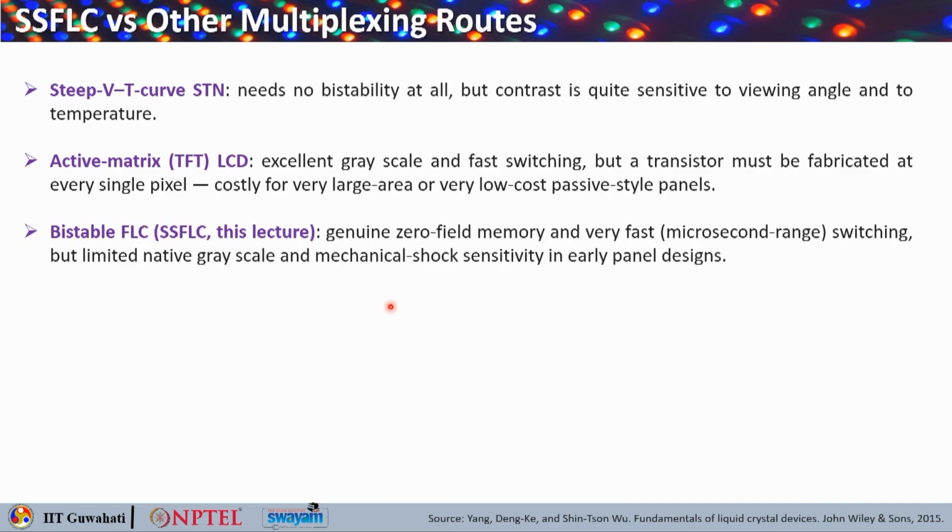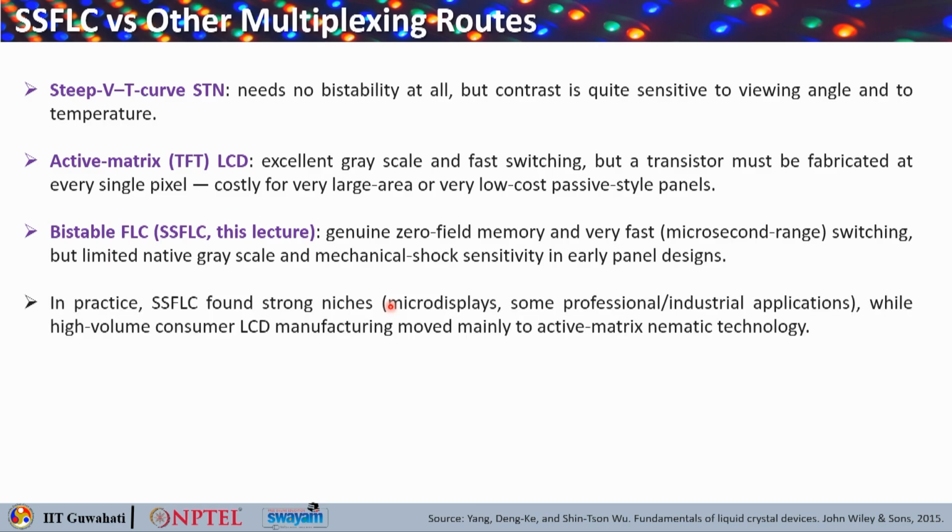This is why our bistable FLCs, that is the SSFLC that we are considering here, show genuine zero field memory and they are very fast. They typically work in the microsecond range switching. However, they have the problem of limited native grayscale and mechanical shock sensitivity in every panel design.